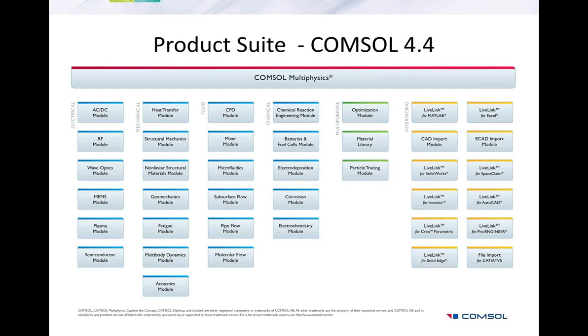How does COMSOL actually model a free surface? Okay, so we use an alternating Lagrangian Eulerian frame to move the mesh on the surface, and the surface moves because of an imbalance of the surface tension forces.